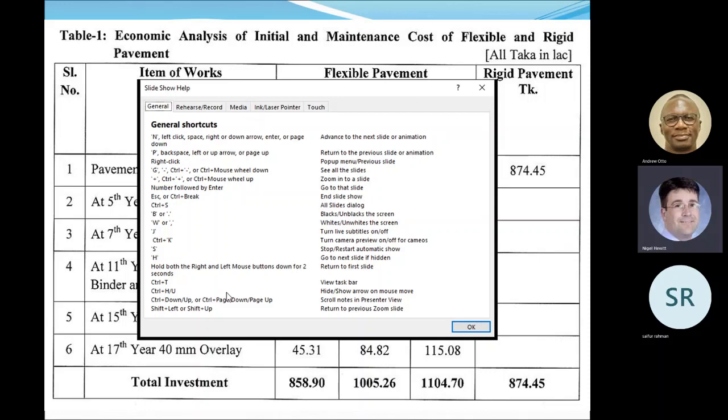And if you compare, say, the running project of Dhaka Sylhet Highway, where the design has concrete pavement in the further sections and flexible pavement in the other rural sections, you must see that now the cost of concrete pavement is less compared to the flexible pavement. Concrete pavement is cheaper, even in the initial cost, if we compare with the provision of the asphalt with PMB. I have done it. The comparison is with me. Thank you.